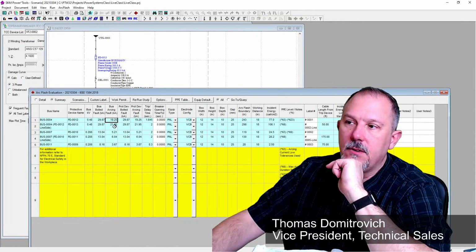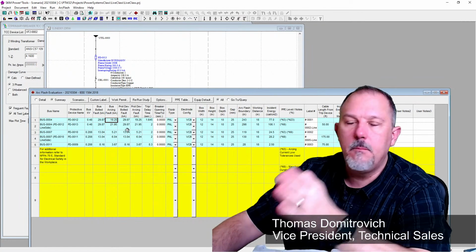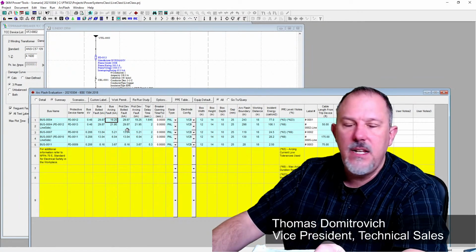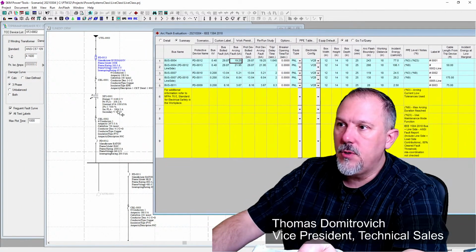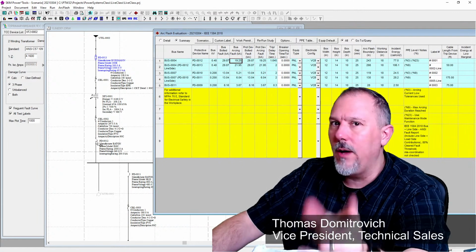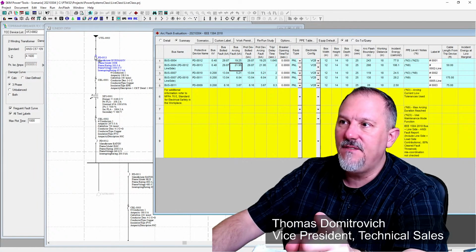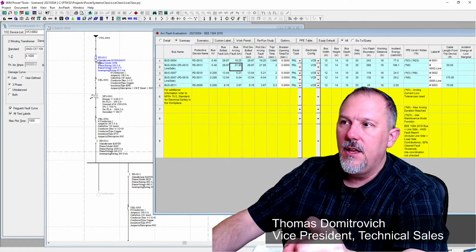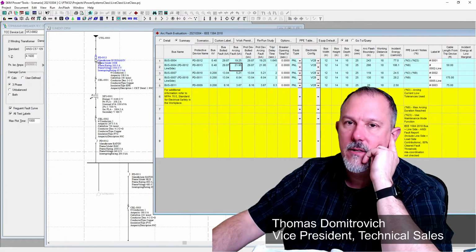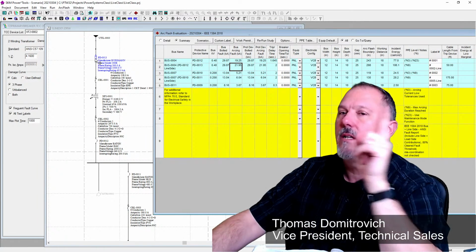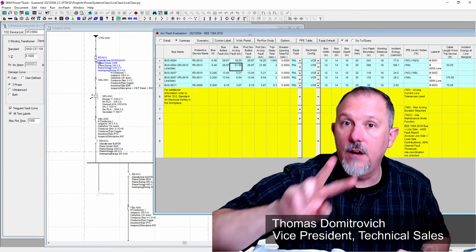And then you'll notice, look at this. The arcing current is different. Why would it be different? It's the same bus. Why would I have 19.25 kiloamps when I'm using PD12 to do my incident energy calculation, but 21.95 when I'm using the upstream fuse for my clearing time? The reason is IEEE 1584 has us calculate two values of arcing current.